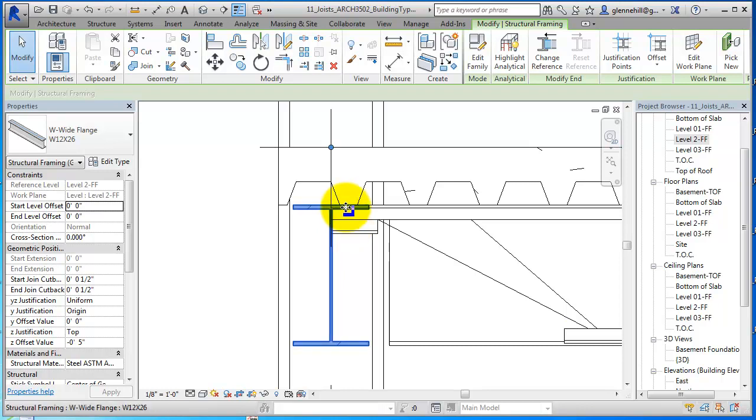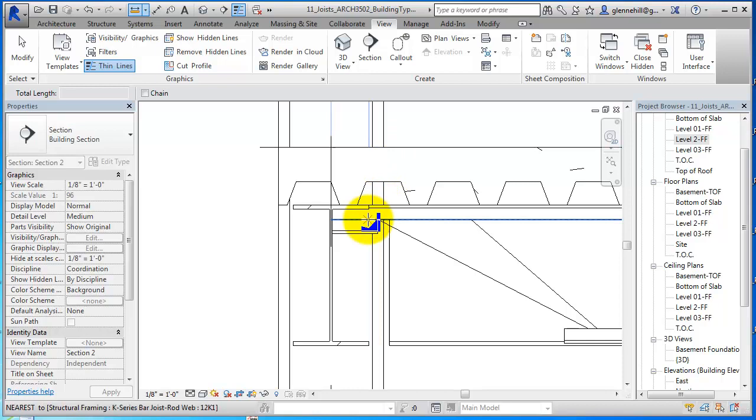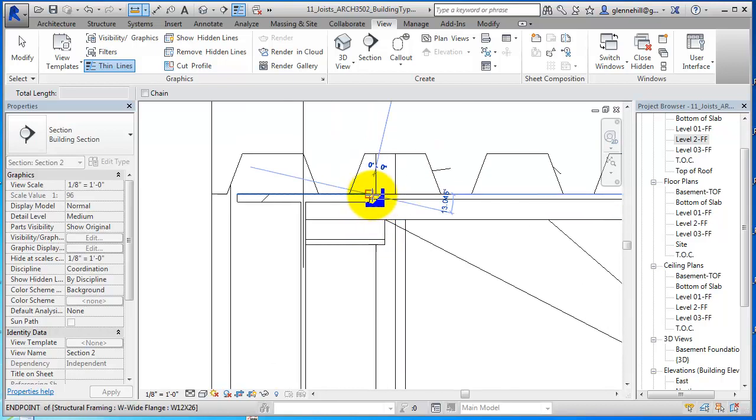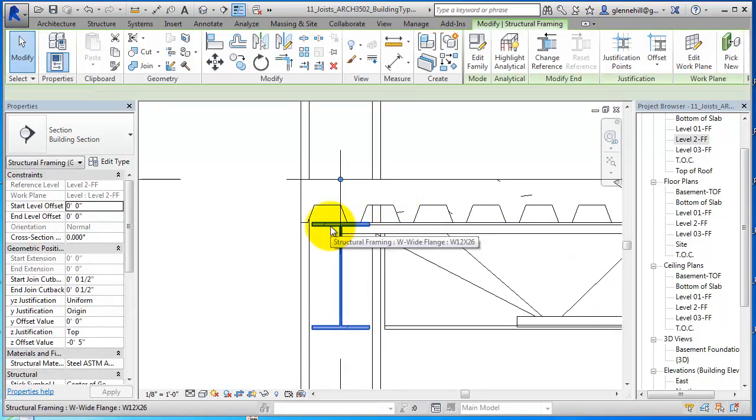Okay, because, remember I mentioned this, it technically needs to be 5 inches below there. So I'm going to go back in here, and actually it needs to be that distance lower. And so let's measure that distance and see what it is. So I'm just going to go from there to there, and it's 2.5 inches. Okay. So if it's 2.5 inches, then what we're going to do is take this and drop this by 7.5.